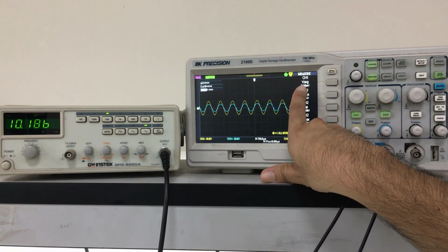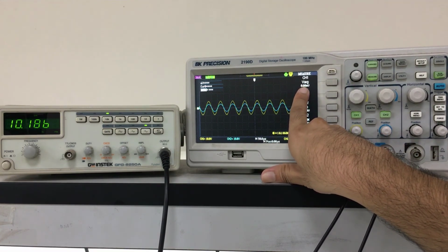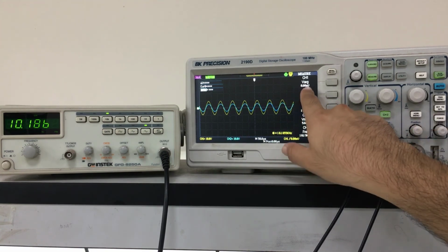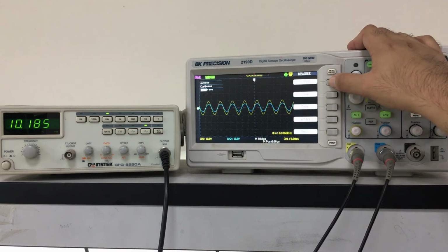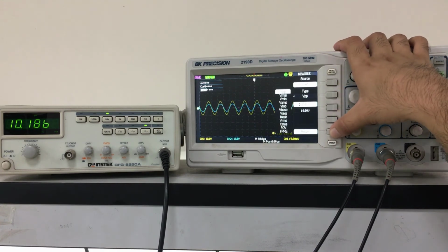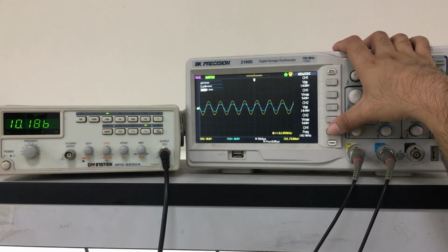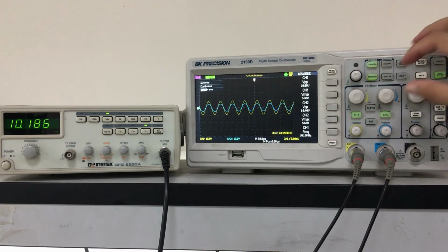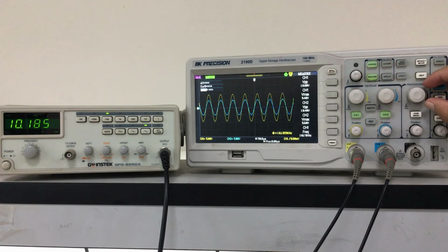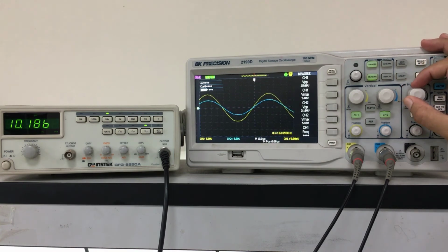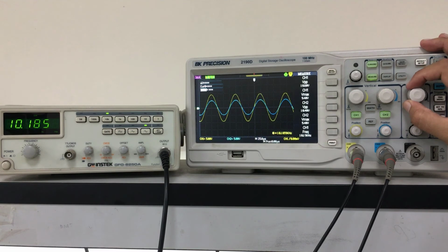Here we see channel 1 V average. We have to change it to channel 1 V peak to peak. Okay, we can set channel 1 V peak to peak here by pressing this button, going to voltage and taking this to voltage peak to peak, which is currently 18 volt. Okay, so I decrease the volt per division, and then increase the time per division a bit.